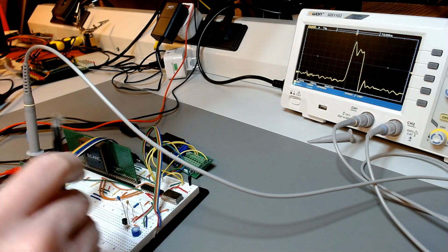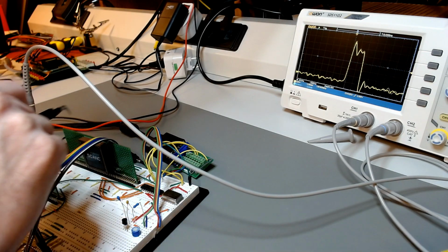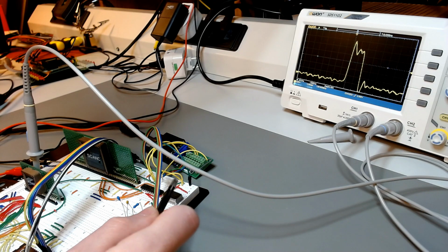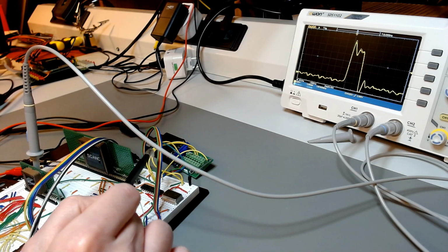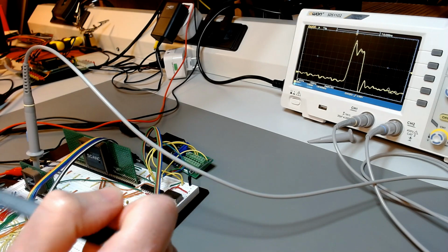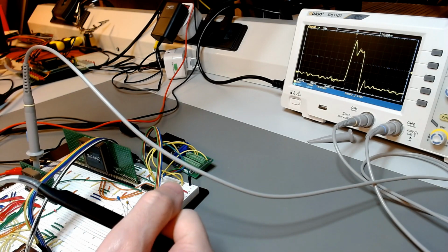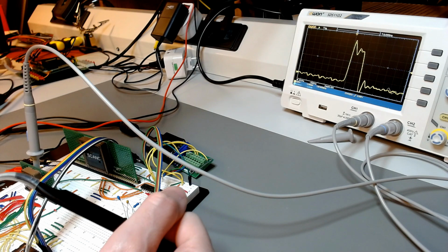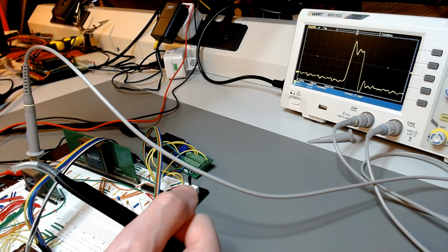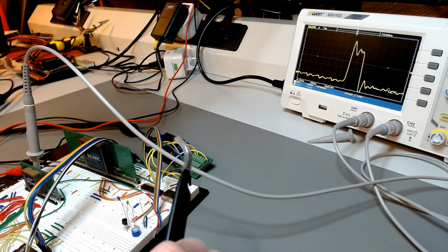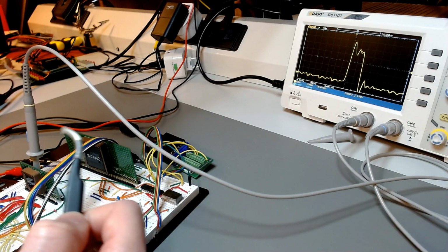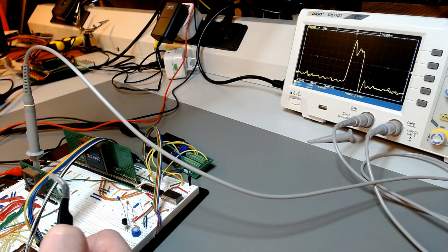Remember, this part of the circuit here operates at over 25 megahertz. It starts being testy for a little breadboard prototype. Normally 8-bit computers don't operate at more than 3.5 megahertz in the case of a Z80, or even less than 2 megahertz in the case of a 6502, which does more per clock cycle. So a breadboard prototype is perfectly alright.